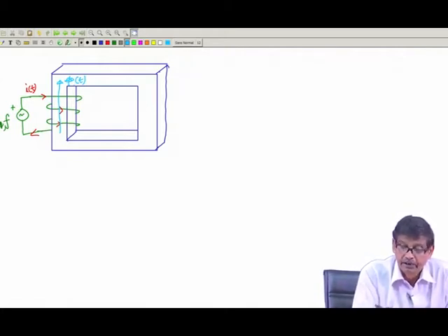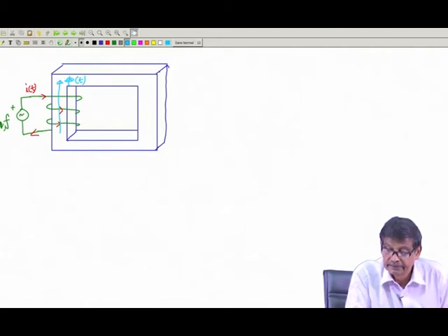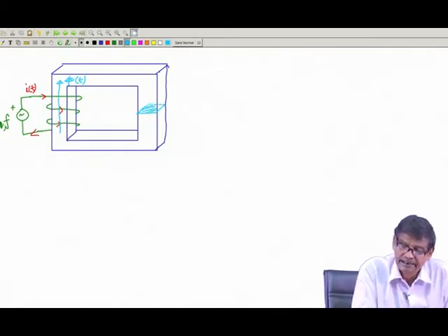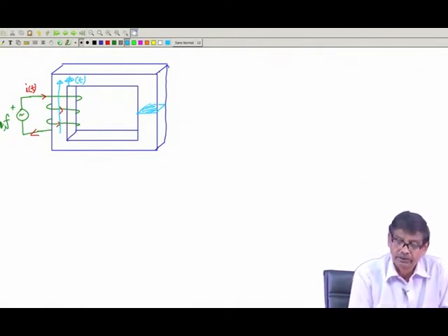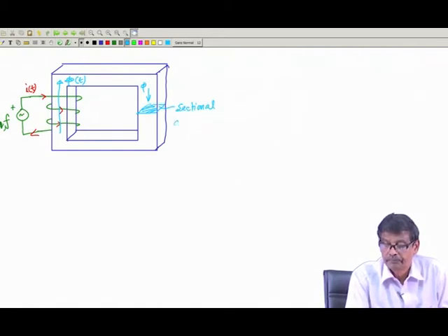Okay. And the cross sectional area of the core is a rectangle, that is these areas. This is the area, and this area let us assume is constant throughout the core. So, flux will be flowing perpendicular to the area. Any area you consider, that flux is crossing perpendicular to that area. This is called the core area, the sectional area of the core.